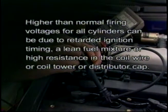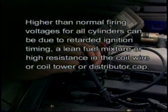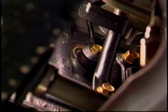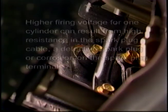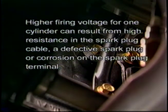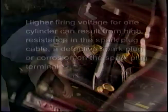Higher than normal firing voltages for all cylinders can be due to retarded ignition timing, a lean fuel mixture, or high resistance in the coil wire or coil tower or distributor cap. And if the cause is retarded ignition timing, don't overlook an over-torqued knock sensor that will retard ignition timing. Higher firing voltage for one cylinder can result from high resistance in the spark plug cable, a defective spark plug, or corrosion on the spark plug terminal.